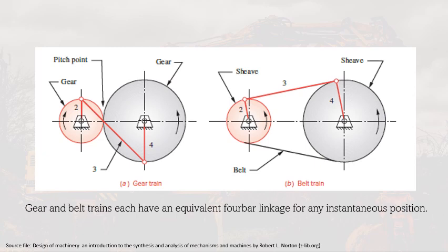The principal drawbacks to the rolling cylinder drive or smooth belt mechanism are its relatively low torque capability and the possibility of slip. Some drives require absolute phasing of the input and output shafts for timing purposes. A common example is the valve train drive in an automobile engine. The valve cams must be kept in phase with the piston motion or the engine will not run properly. A smooth belt or rolling cylinder drive from the crankshaft to camshaft would not guarantee correct phasing. In this case, some means of preventing slip is needed.